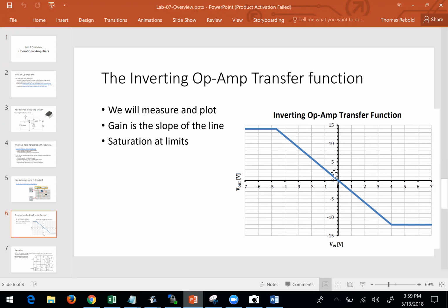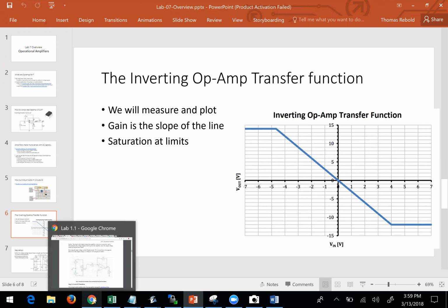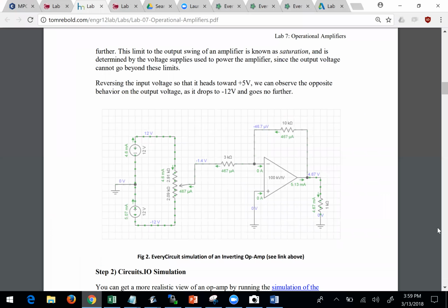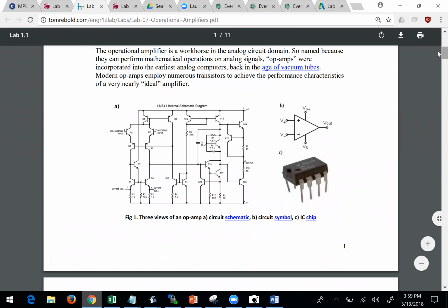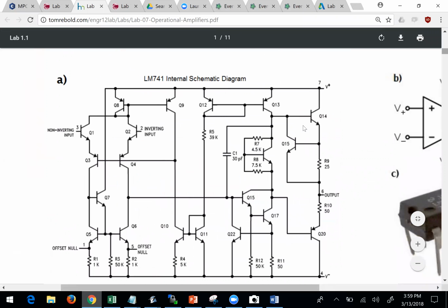Why wasn't the saturation like 10 volts-ish? But when I measured the end, it got up to 12. Yeah, I got up to 11.1 on somebody's. So the question is, why didn't it go to 12.3 or something, right? Well, the circuit inside an op amp is a transistor network. It's a bunch of transistors. And remember when you did that experiment with diodes and you measured the voltage drop across the diode, at what voltage it turned on was around 0.7 volts or so? Do you remember that?